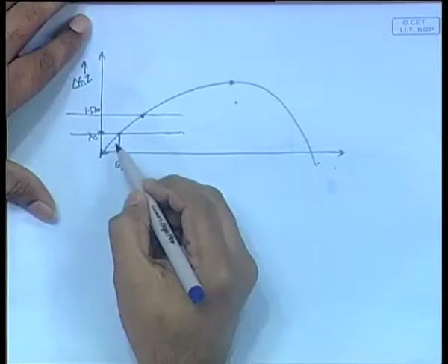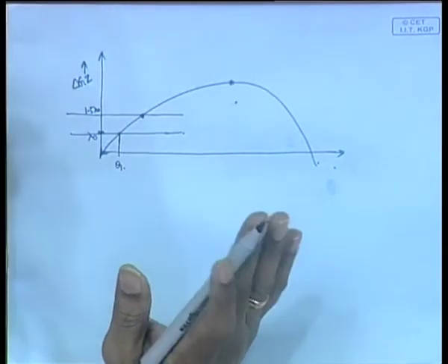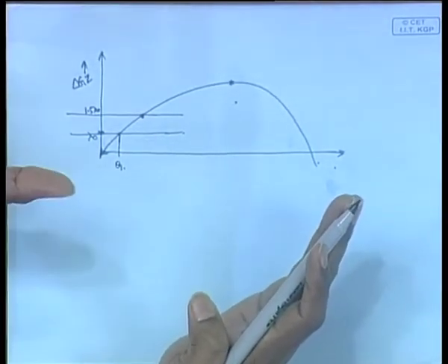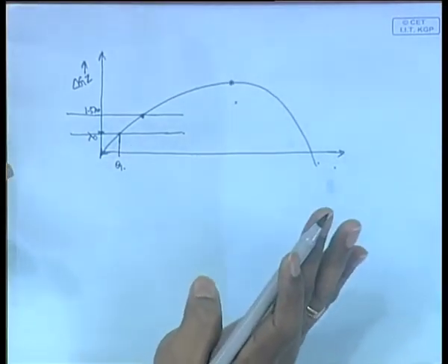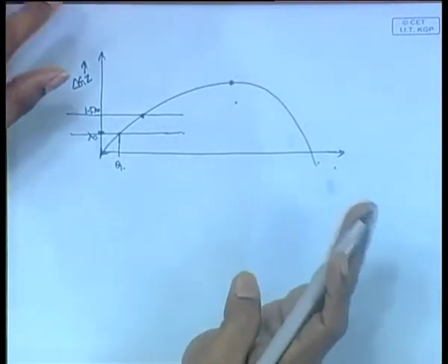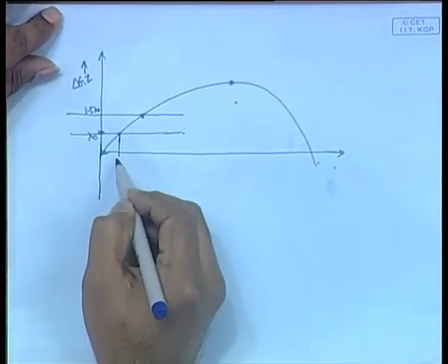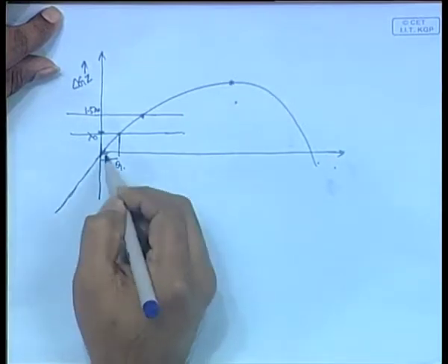So, at lambda 0 it is heeled, we assume that because of this wind it has heeled by a maximum of 15 degrees. The exact reason for the 15 degrees is not necessary, but assume that it has heeled through 15 degrees. Therefore, it has heeled from here, we have to extend this GZ curve. Okay.